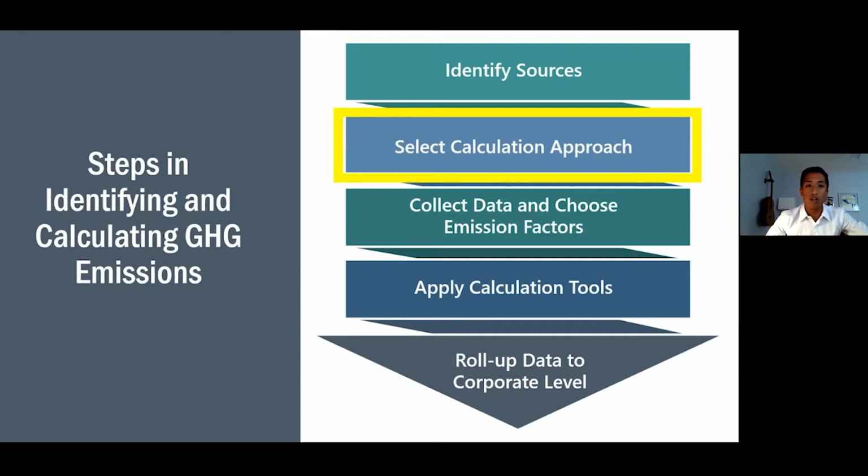So there's multiple ways. There's direct measurements using CEMS devices. So usually you'll see these in refineries, but all facilities aren't implementing CEMS. So more often emissions can be calculated using mass balance or stoichiometric bases specific to a facility. But the most common approach is the use of emission factors. There's a lot of data out there. EPA has a guidance document called AP-42, which has source-specific emission rates. And these rates can be used for calculations of your greenhouse gases where necessary.